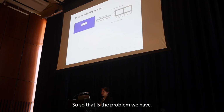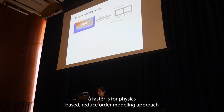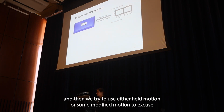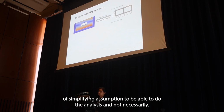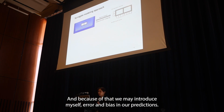So that is the problem we have, and one approach that we usually use to make these analyses faster is the physics-based reduced order modeling approach, where we replace the surrounding soil with a set of spring models, and then use either free field motion or some modified motion to excite these springs and get the response of the buried structure. But in many cases we need to make lots of simplifying assumptions to be able to do the analysis. Not necessarily are these spring models and input motions ready to use, and because of that, we may introduce lots of error and bias in our predictions.